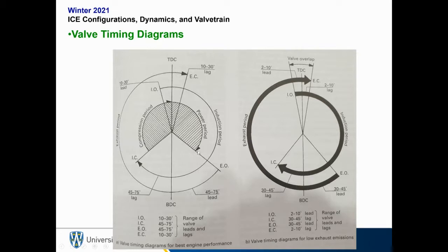And actually the exhaust valve opens partway through our power stroke. So the piston hasn't even gotten all the way to the bottom, and then we're opening our exhaust valve. And then the exhaust valve actually stays open for quite a long duration and into the intake stroke. So to say that a 4-stroke engine is an engine that has 4 distinct phases where each stroke is completely isolated, well, that's not really true. There's overlap between the exhaust and the intake and compression.